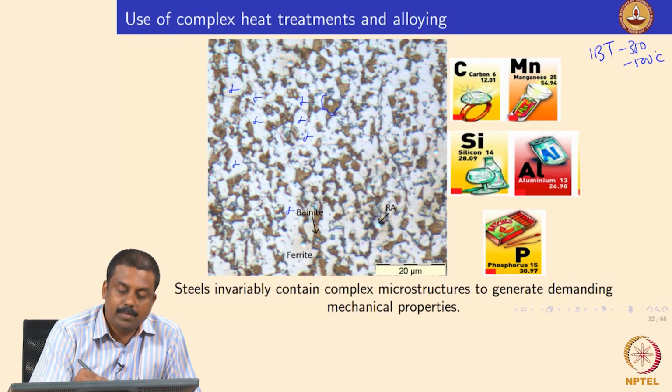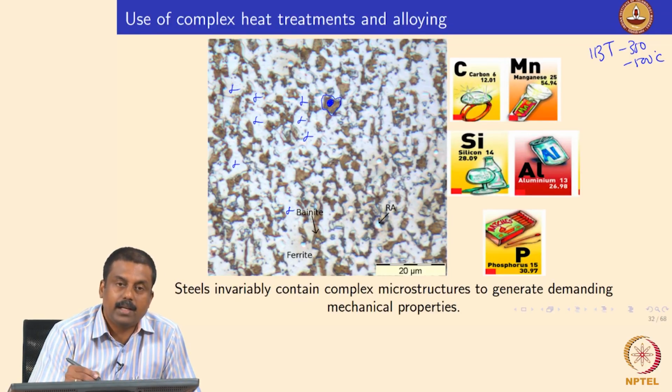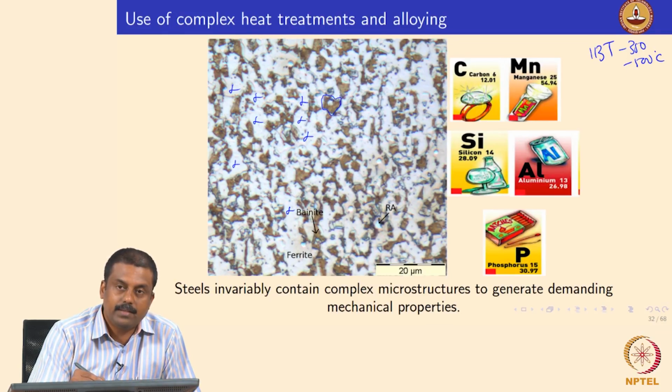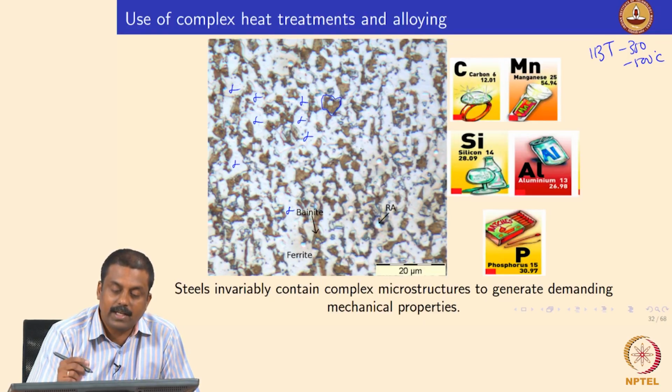Okay. So, say for example, this was a prior austenite grain boundary. It will be transforming some of this austenite into bainitic ferrite, and during this process we push the carbon atoms to the untransformed austenite. Upon sufficient enrichment of carbon the bainitic transformation ceases, and the carbon concentration of this austenite is so high that upon subsequent cooling to room temperature it cannot transform to martensite, because the Mf temperature is lower than room temperature. This austenite is then retained as retained austenite. Now this microstructure contains 3 phases, right.